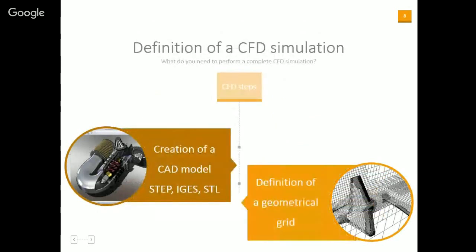In our software, we define 4 phases. The first one is the CAD phase, is the phase in which you generate the geometry and select how to define it. Then there is a geometrical phase in which you subdivide your fluid volume into geometrical entities such as cubes or triangles, and in this way you can create a mesh or grid.